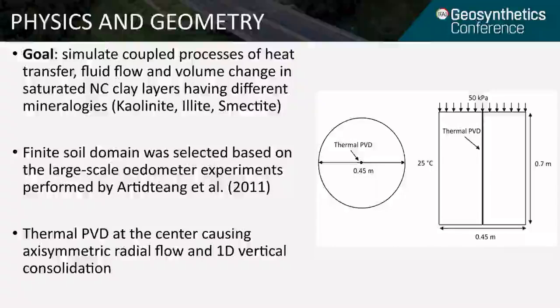Although thermal PVDs have been tested in proof-of-concept field experiments, there are still several variables and soil behavior that need to be characterized better. With that in mind, the main objective of this work is to simulate coupled processes of heat transfer, fluid flow, and volume change in saturated, normally consolidated clay layers with different mineralogies. Specifically, we considered clay layers of kaolinite, illite, and smectite.